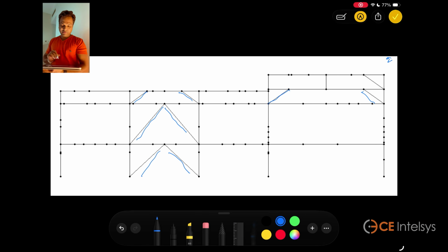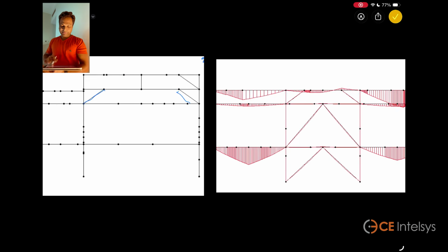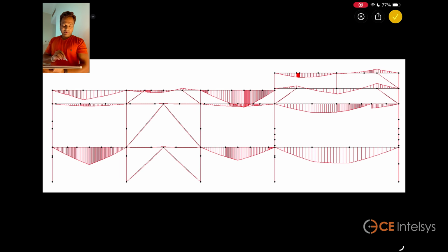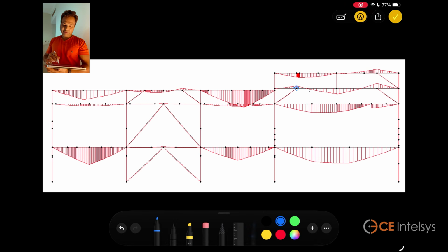So now I have to define LZ for this elevation or these horizontal beams. What I will do, I will apply the self-weight of all these structural members in the vertical Y direction, downward, and examine what is happening with the bending moment diagram. Okay, so this is the applied load and bending moment diagram. So what is happening with the self-weight of these members? We can find that certain kinks are formed. There is a change of direction of the bending moment at the brace point locations here.